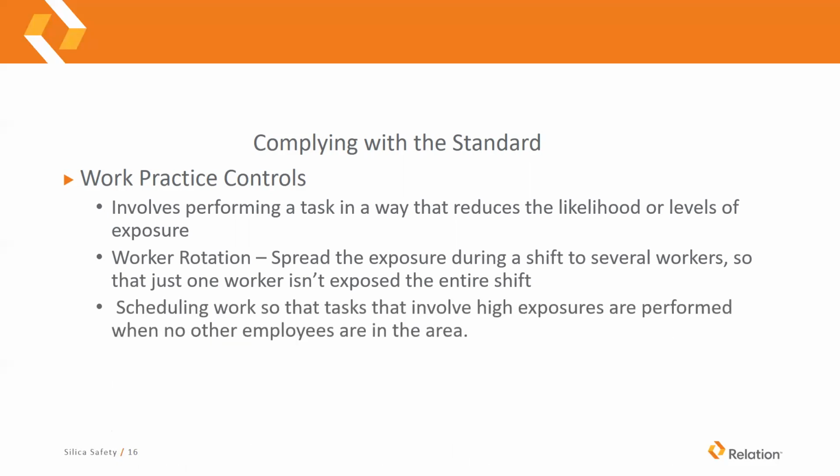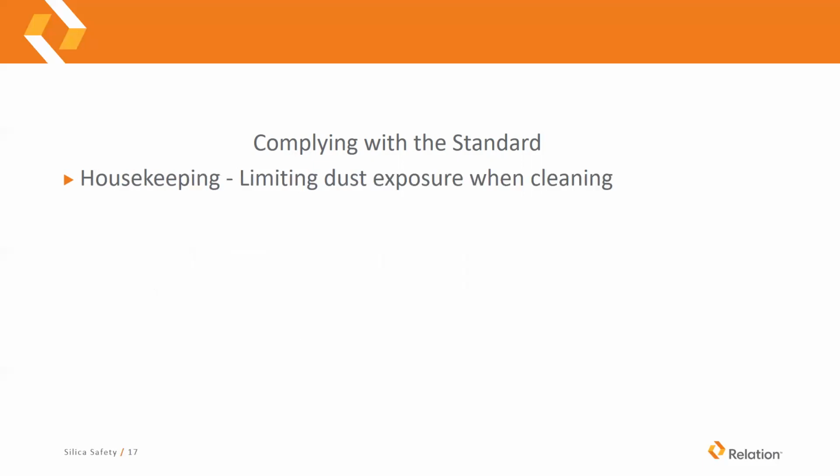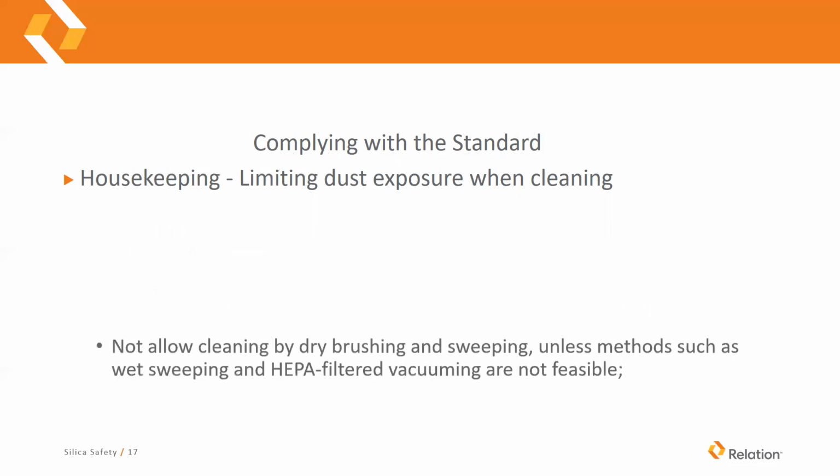Scheduling work so that tasks that involve high exposures are performed when no other employees are in the area. So if you have somebody that's doing a lot of drilling, you can bring them in towards the end of the day, or you can bring them in early when there's not a whole lot of people around. And housekeeping. So limiting dust exposure when cleaning.